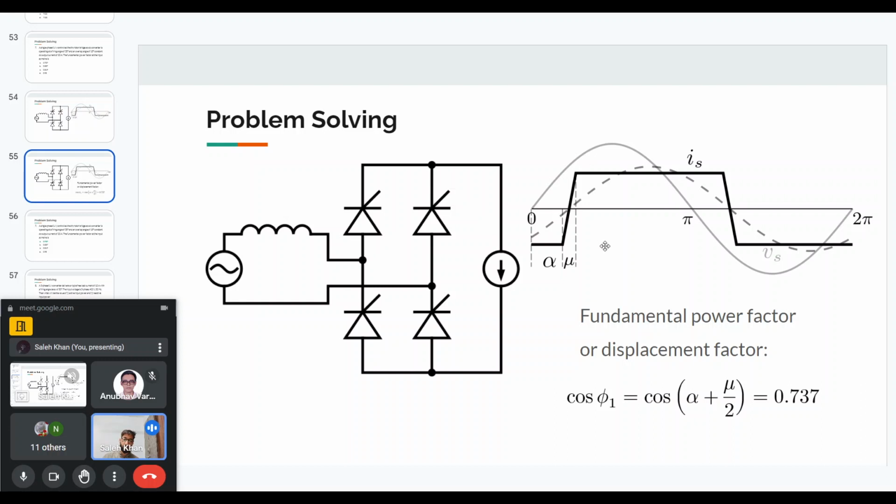Then you can find out the power factor, and that may improve, because the power factor expression does not only depend on the angle, but also on the fundamental divided by the total RMS. In that case, that current may increase. So the power factor may improve.